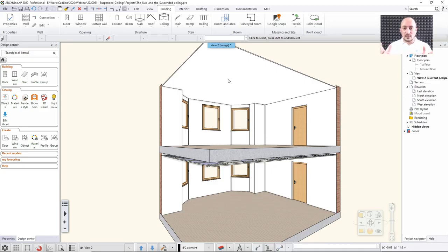You already have the room, and you can furnish it if you would like to create an interior design for a simple room. But if you design the building itself, it still makes sense to create ceilings, even though most of the time with certain types of structure, the slab itself behaves as a ceiling. But if, for example, in our case, when we design an office building where we have a grid ceiling above us, or we have an interior structure where, besides the regular slab and door and window and wall connections, we also have some sort of decorative, acoustic, or any other reasons to create a suspended ceiling, then we can also use that tool. So it has two purposes.